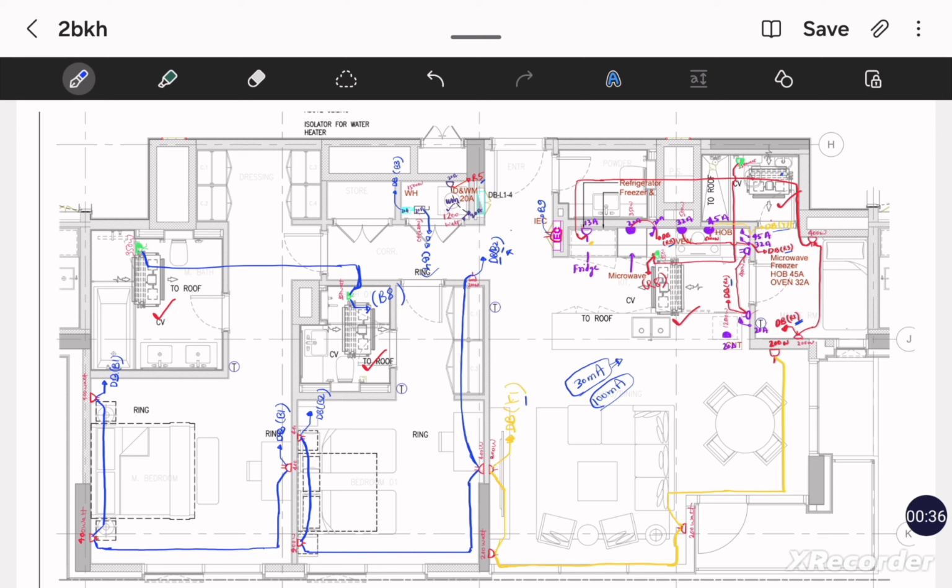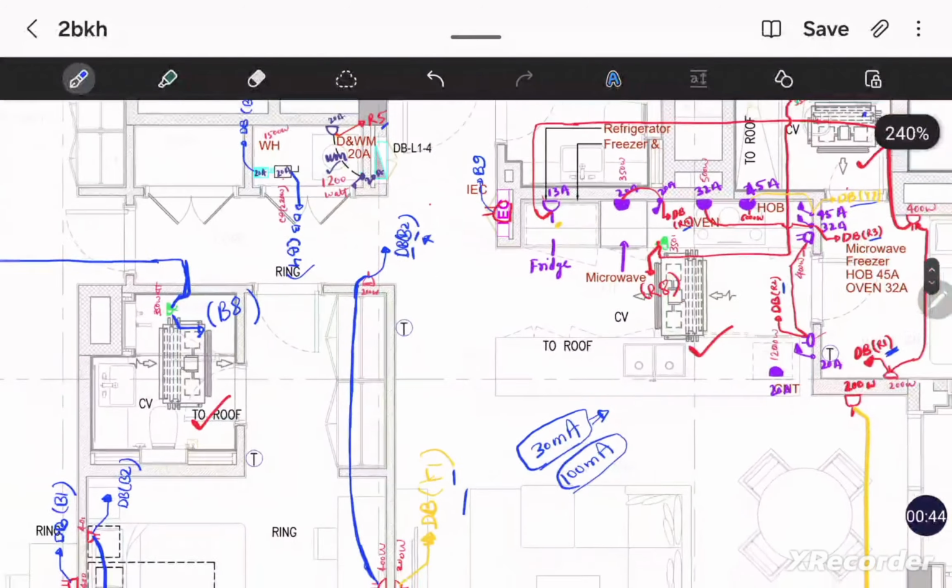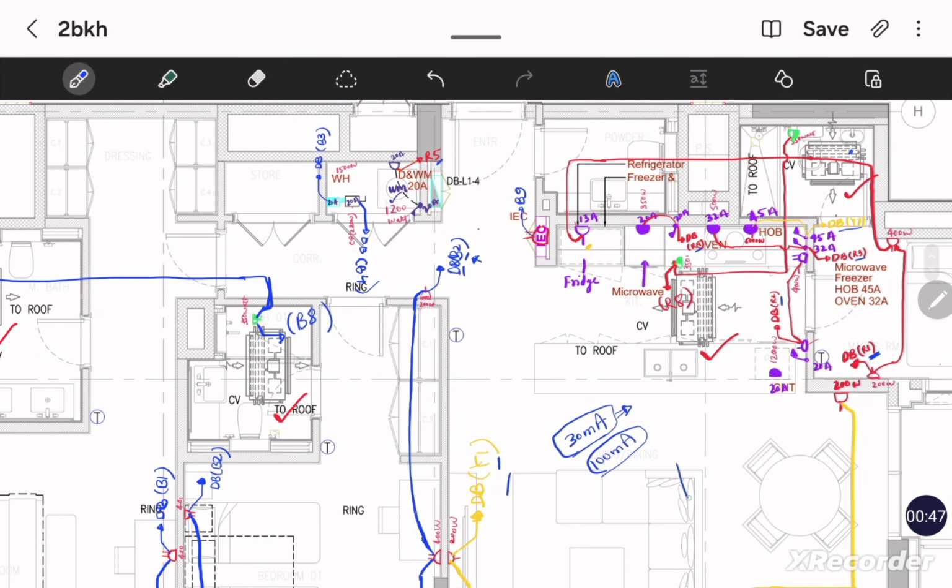That will be a different case. Now we have given the circuit numbers to the Y phase, that is Y1 and Y7. As I told you in the beginning, I will make a load schedule in which the first circuits will be for the power, then for the light, and then again for the power. That's why I mentioned Y7, just after Y1. You will understand this when you practice designing.